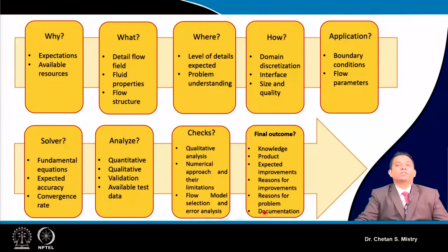Now documentation of what we have done is very important. So overall, computational fluid dynamic analysis for an axial flow compressor or fan demands all these aspects, and we must realize why we are doing this analysis. Many times people say CFD is a design tool. It's a misconception. What we have done in the last 11 weeks is your aerodynamic design, your preliminary design.